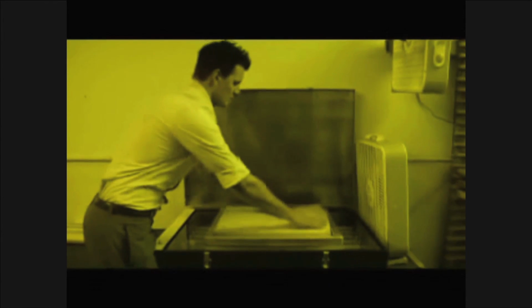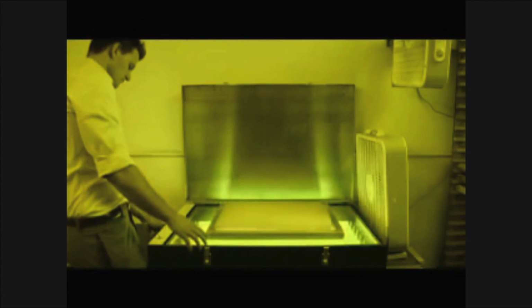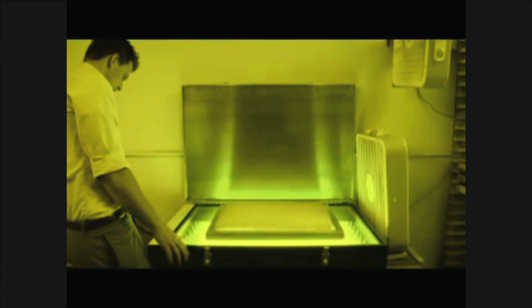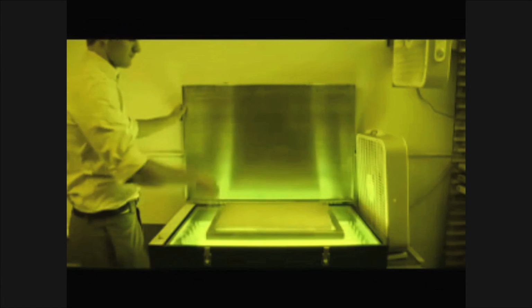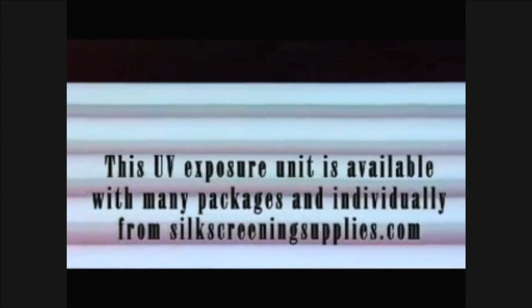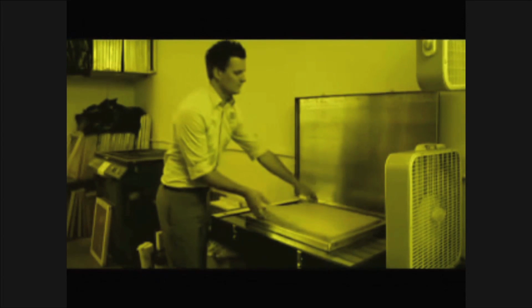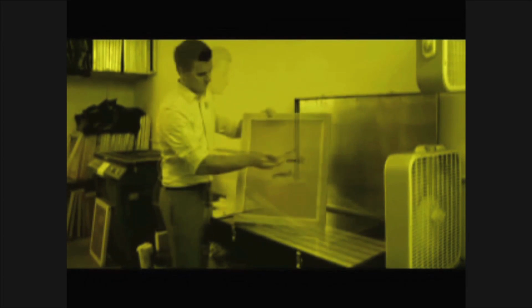There are many types of exposure units on the market. Today, Ryan is using an automated UV exposure unit manufactured by Ryonet and available from our website. This unit is very effective and comes with a timer for convenience and highly accurate exposure times. Place your screen with the artwork taped onto it, face down, and expose for the appropriate amount of time for your particular screen.